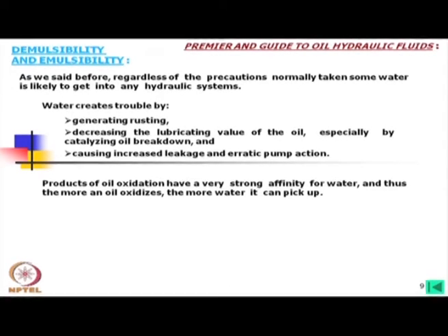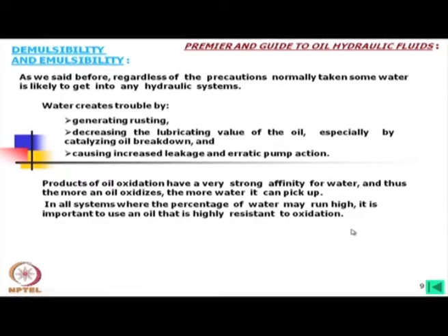In this case for water there is no cavitation, but it will change the oil specification like API gravity and the viscosity, and then pump action may be erratic. Products of oil oxidation have a very strong affinity for water, and thus the more an oil oxidizes, the more water it can pick up. You see, this is another point, it can easily take water due to the oxidation.